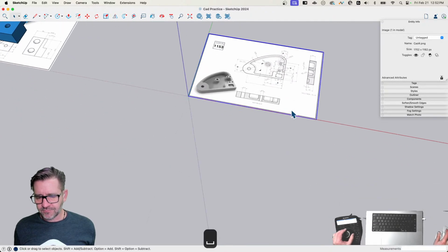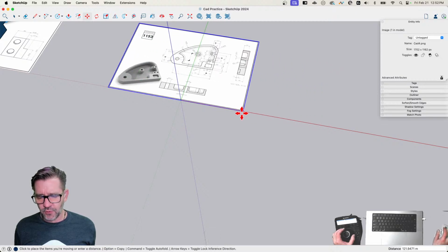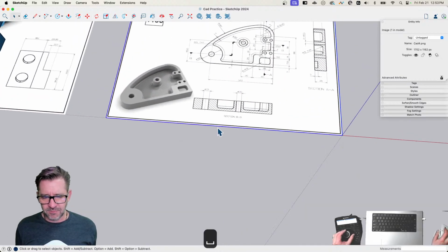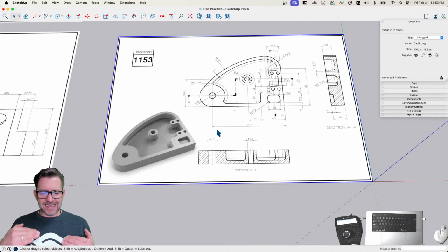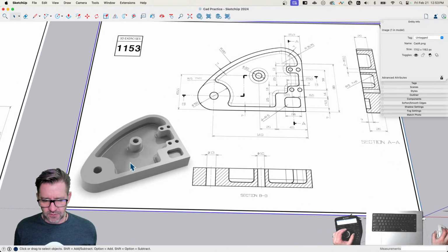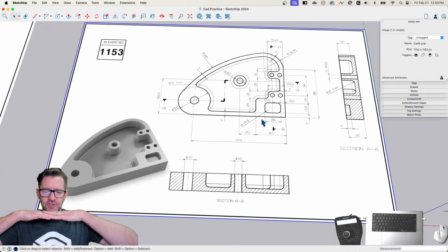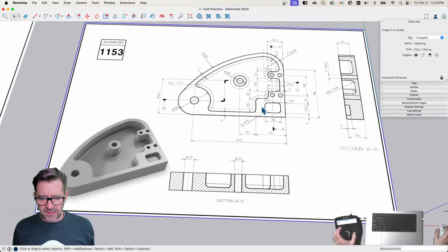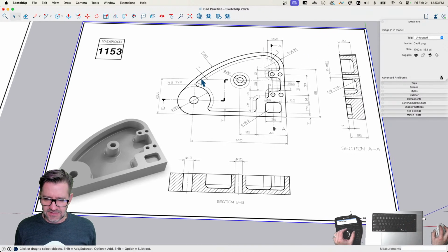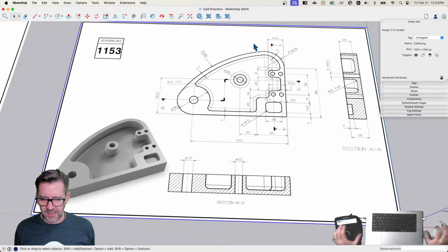All right. So again, here's my real quick breakdown of this model. This model is, again, essentially a plate. So this outside shape right here, I would draw this on the ground. Then I would go in and take out all the circles and push it up that initial depth. So whatever this number here ends up being, pull that amount up. Then I'd go in and get this inside wall and pull that up to get this top piece.